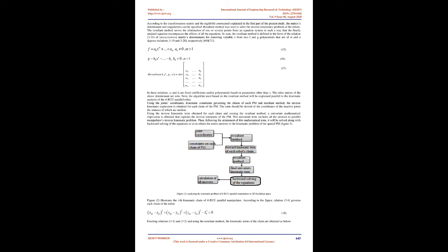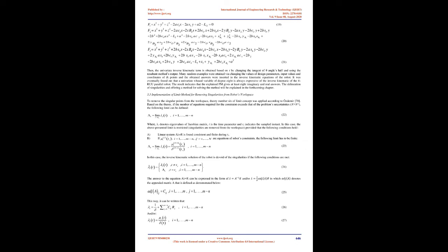Considering a variable change equal to t = tan(θ/2), the following relations are obtained. And the coordinates of point Ci and the vectors perpendicular on plane Ni defined in the fixed coordinate system are as follows. The coordinates of all points should be obtained based on geometrical parameters and spatial coordinates parameters. The link connecting Bi and Ci is on the same plane as vectors Ni and Bi, and the constraint equations are acquired via scalar multiplication and external multiplication.